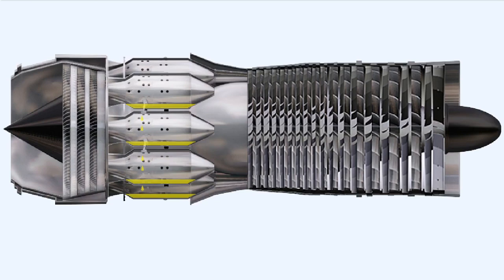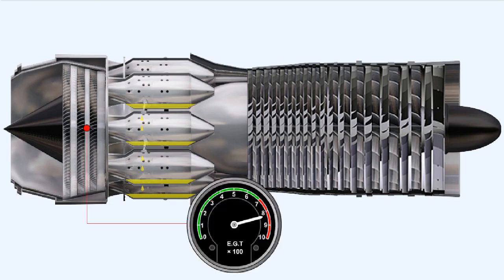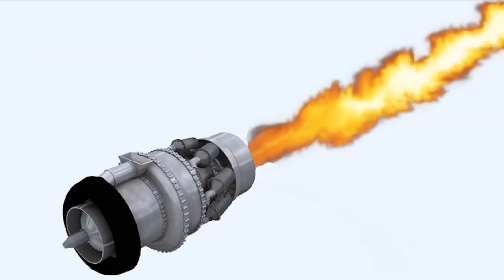A considerable amount of fuel will have been fed into the combustion chamber during the attempt to start. If that fuel is not removed before the next attempt to start, and if that attempt is successful, the result will be a combination of excessively high gas temperatures in the turbine region and torching, which is the name for a very long, very hot, and very dangerous jet of flame issuing from the rear of the engine.